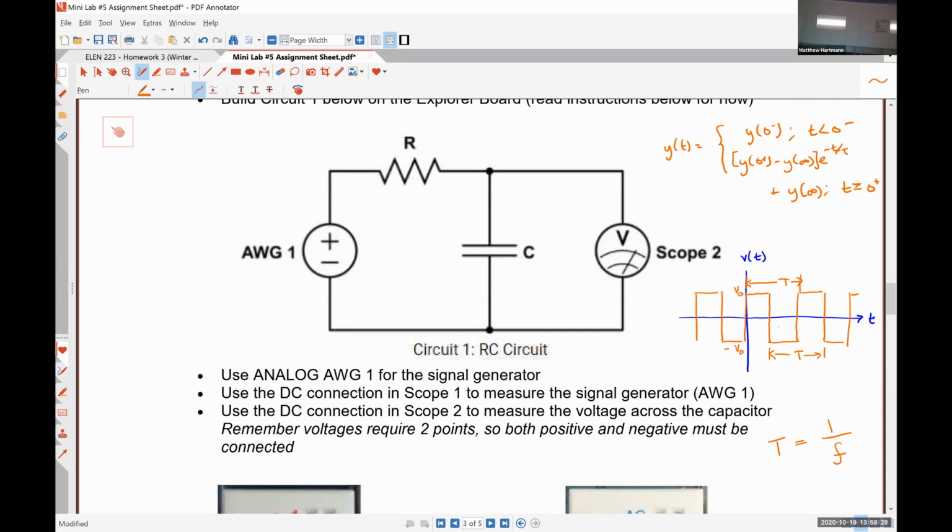Okay? So the fundamental definition of the time constant is how long it takes to decay from one value to e to the -1 times that value. That's one time constant. So it's a reduction in signal strength by, I think, 37%. In 2 time constants, it decays down to around 13%. And 3 time constants is around 6%. And 5 time constants is what an engineer considers to be infinity. So it's decayed to less than 1% of its original value. So we say that it's close enough to its final value.